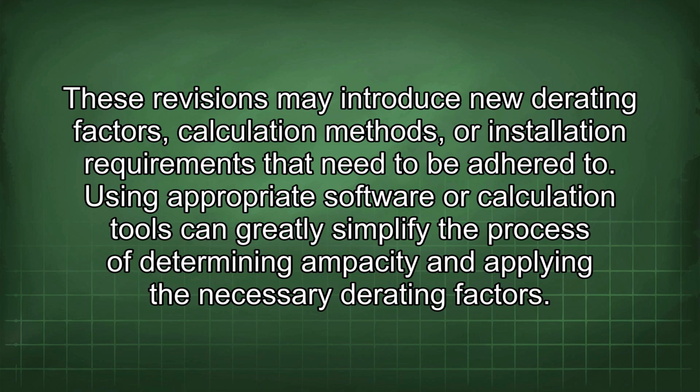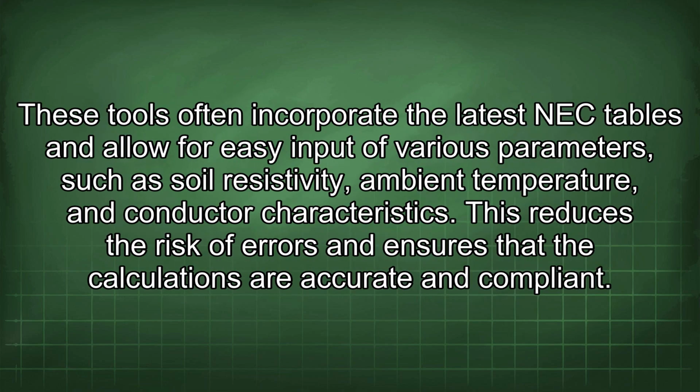Using appropriate software or calculation tools can greatly simplify the process of determining ampacity and applying the necessary derating factors. These tools often incorporate the latest NEC tables and allow for easy input of various parameters such as soil resistivity, ambient temperature, and conductor characteristics. This reduces the risk of errors and ensures that the calculations are accurate and compliant.